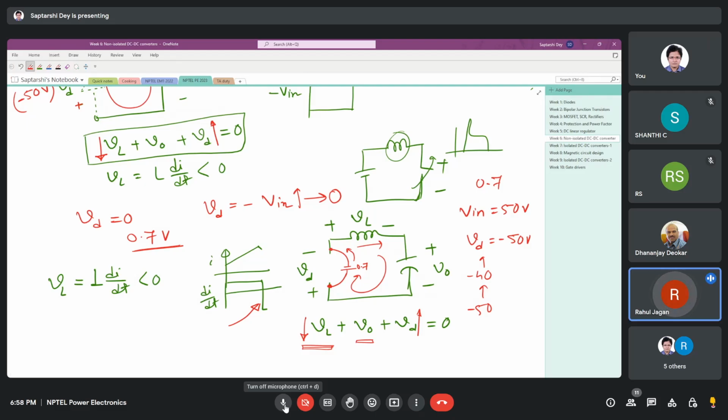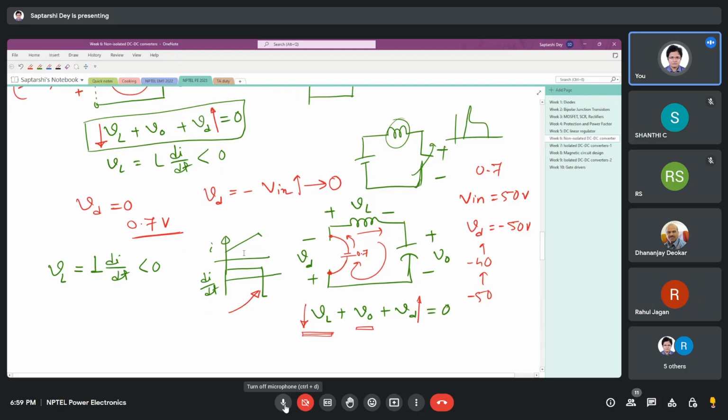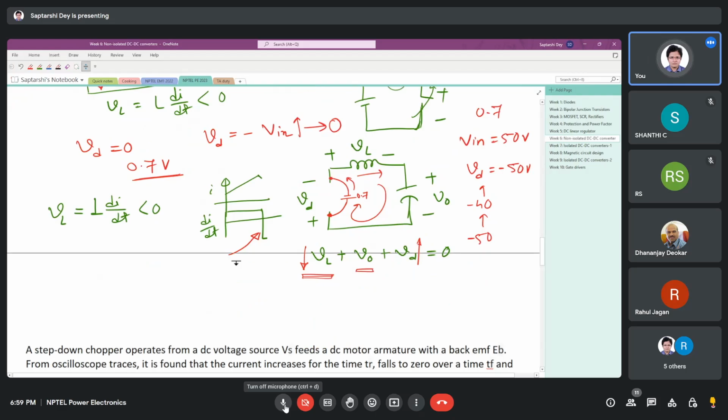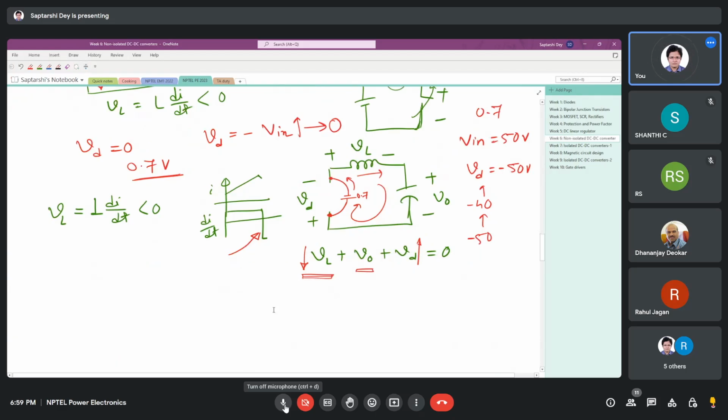But here the current which is showing is the inductor current, and the downward is inductor voltage. In inductor, the current lags the voltage. Where is that in the graph? Okay, it looks like you missed those initial classes. Inductor current lags voltage, all these things are not in this waveform. Those things are all valid for steady state AC circuits.